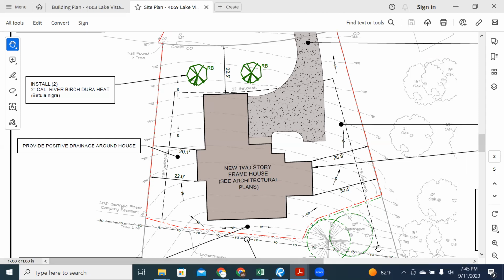By the time you hit here, you're at 800. So you're almost about 4 feet, 5 feet from this level where your house is to the back here. Now we dug this down in the back so that we can be at the same level, roughly at 795, so we can have a leveled foundation.